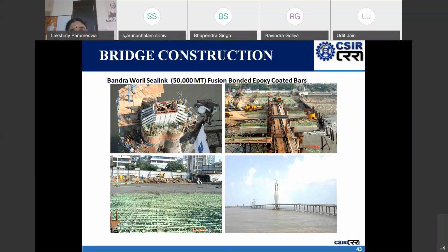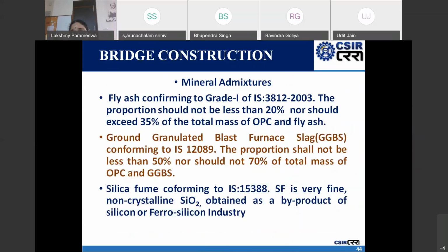about its use, because the handling, transporting, etc. should not damage the reinforcement, and how we store them at site is also important. If pinholes are formed, then that becomes a local location from where corrosion can be initiated. So one has to be very careful, because these are barrier coatings. And another problem with this type of bar is that it reduces the bond strength, so we may have to provide additional development length.